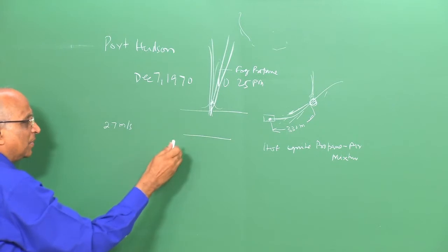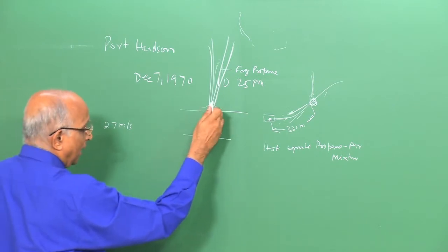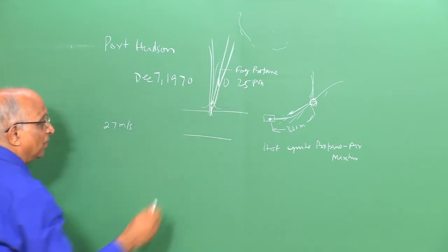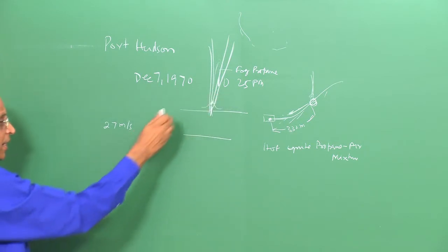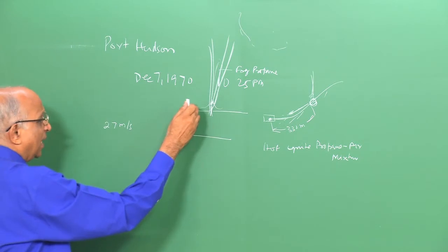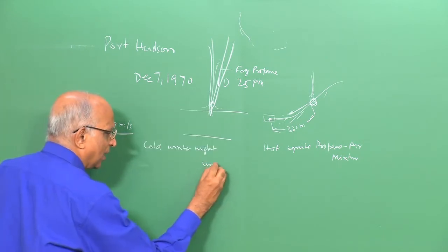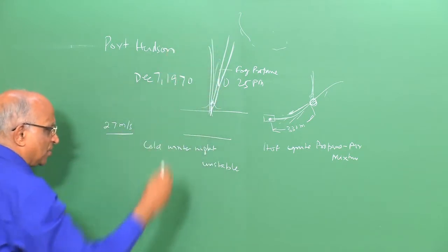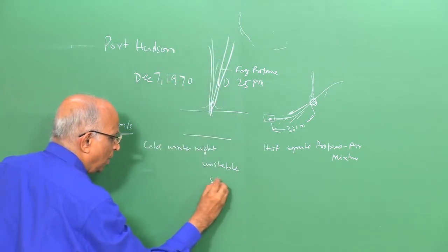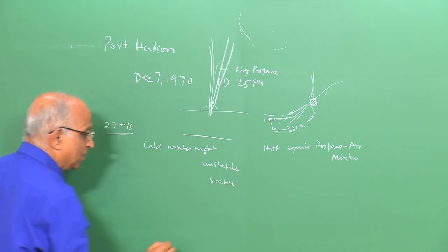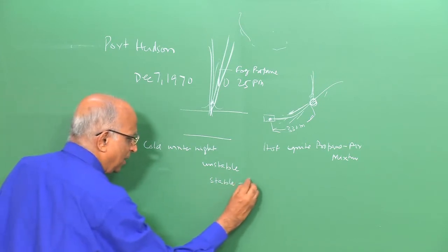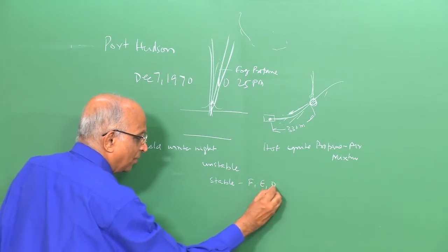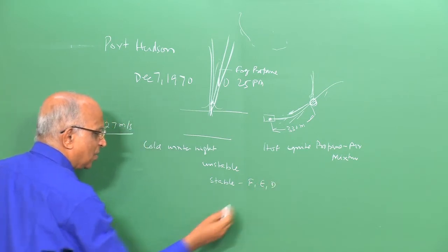Therefore we have atmospheric inversion, that means a positive temperature gradient above the surface. We looked at unstable atmosphere, wherein anything gets dispersed away. On a cold night the atmosphere is stable; you could have extremely stable, moderately stable, or very weakly stable atmosphere.